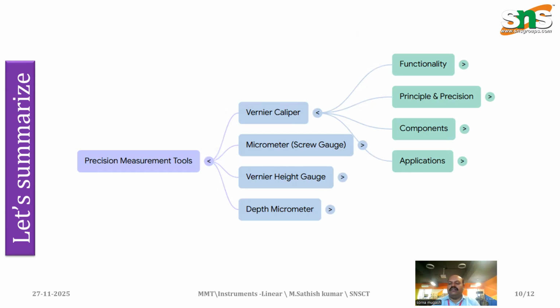Likewise, every component in the automobile sector will have a different kind of components, and those components will have an engineering drawing and the dimensions are mentioned by the designer. The person who is in quality checking has to ensure all the component dimensions are measured properly and everything is within the tolerance limit, that is the acceptable limit.